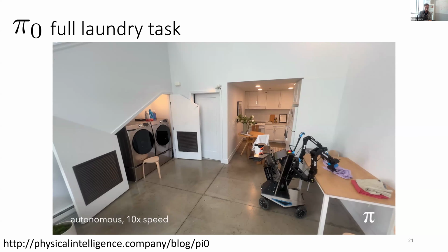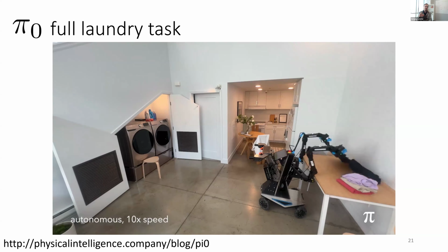We've been experimenting quite a bit, actually, with more dynamic tasks, including things like picking up objects off of a moving conveyor belt. There is some care that needs to be taken there, because as a technical detail, the action-chunked architectures that have been most successful for VLAs do limit the robot's ability to be reactive. So even though the arms are controlled at 50 hertz by the policy, the underlying inference runs much slower than that.